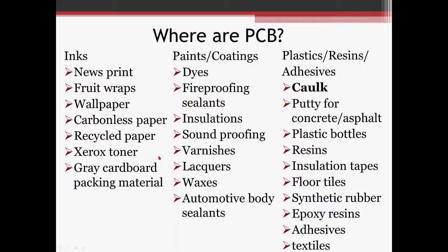You know, we often hear about the caulk materials, and that is a big one. That's become commonplace to sample for that, but there's other building materials that may have PCBs, maybe less common than caulk, but could have the potential for it. So adhesives, different things like that. So you may want to look at sampling those other materials as well. But you know, as you can see, PCB they definitely will put in a lot of things.